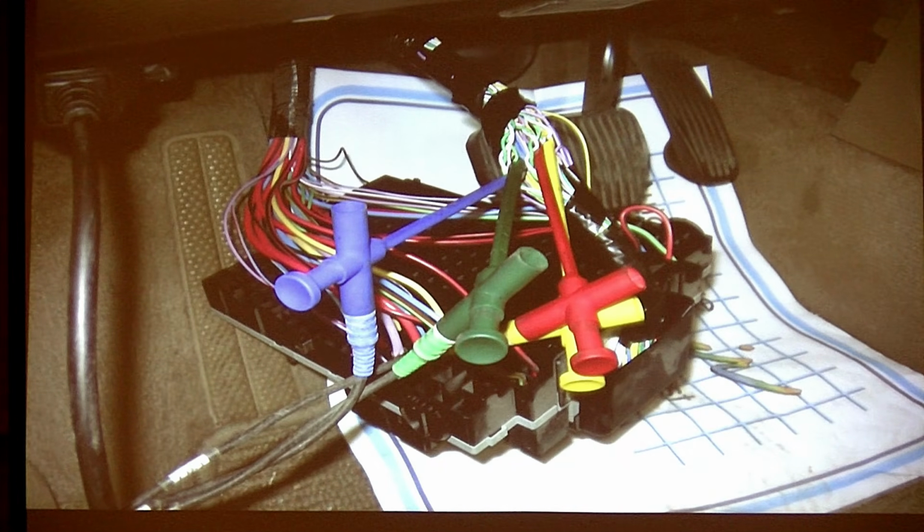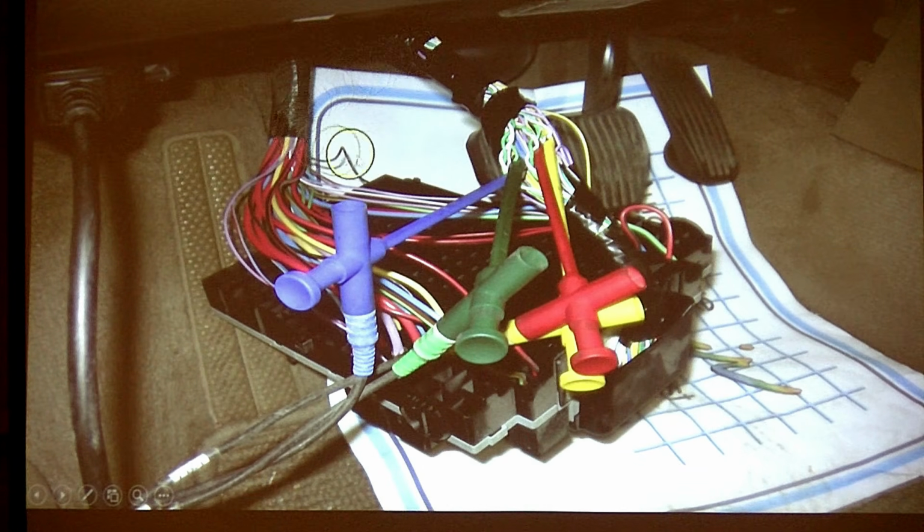Notice I don't have my buddy's breakout box. This is the way I really do it. Okay, you've got to find the wires. I drop the SIM down. The SIM is right under the dash, driver's side. I drop it down and I find my CAN lines right here, and I want to get into my CAN lines, high and low, right? I need both because we're transmitting data across this bus.